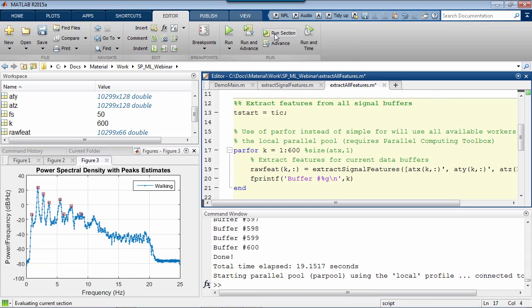The buffers are now processed asynchronously by a pool of 4 MATLAB worker sessions running in the background, and I'm finished in a fraction of the original time. The actual performance gain will change depending on the particular problem. The bottom line is that because I had the Parallel Computing Toolbox installed on my machine, I was able to open locally a number of MATLAB workers equal to the number of available cores on my machine. I have 4 cores here.